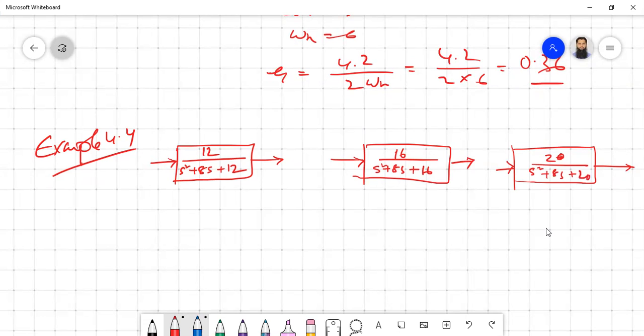Okay, so to figure out, previously, whatever the transfer function we had, that is s square plus as plus b equal to 0, that characteristic equation. So we can actually take help of this one as well if you want. What we know is a equal to twice zeta omega n.